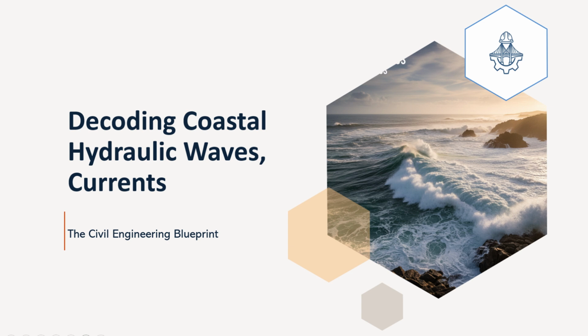These happen on steeper slopes. Here, the crest curls over dramatically and plunges down, often trapping an air pocket. These are often considered the most energetic and potentially destructive breakers, releasing energy intensely in a narrow zone. Great for surfing, maybe not so great for structures.